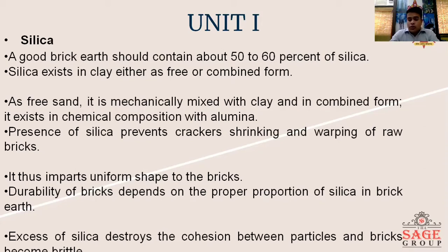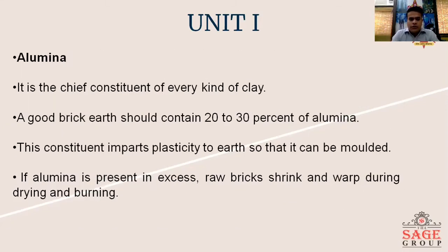That means the durability, how long the brick survives, depends mainly on the percentage of silica. Excess of silica destroys cohesion between the particles and the bricks become brittle. Cohesion is the force in which the particles are bound closely packed with each other. If the cohesion is not working, then on drying the brick gets deteriorated and does not have a regular shape and size. Next comes the second point, that is alumina.